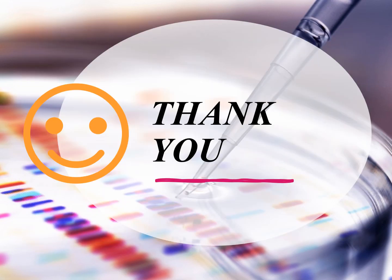In the final equation shown, we have inverted mu over rho DV arbitrarily to conform with the Reynolds number. Hence, we express it as density D times V over mu. So that ends our discussion on dimensional analysis. Thank you for watching the video.